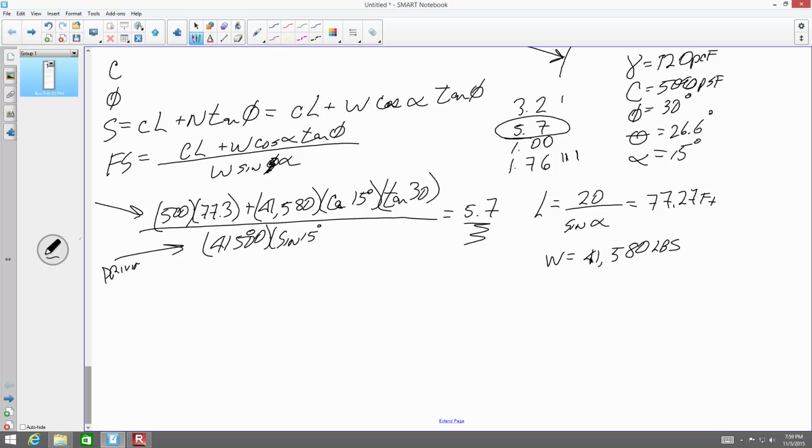So here's a quickie. Do you know it or you don't know it? You're never going to be able to look it up. The liquid limit is determined in the Casagrande cup method by obtaining the moisture content when the number of blows is 26, 20, 25, or 10. So that's how many times we drop the cup to close the groove by a half inch, right? 25 for the liquid limit.